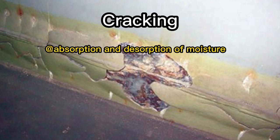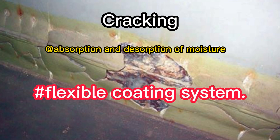The thicker the film, the greater the possibility it will crack. To prevent cracking, use the correct coating systems, application techniques, and dry film thickness. Alternatively, use a more flexible coating system.